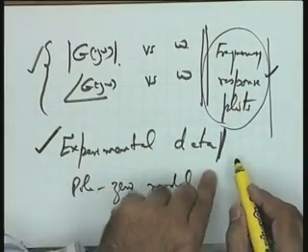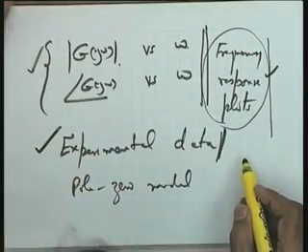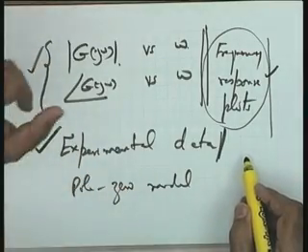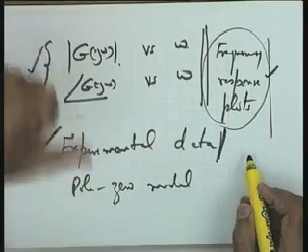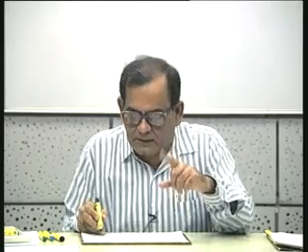So, from the frequency response data which you have got, you are getting a pole-zero model because you want to use the root locus method. However, in the process you have definitely made errors, because a complete mathematical model is not possible, a complete fitting will not be possible. So, you are working on an approximate model when you are going for a root locus formalism. But in the frequency domain formalism, since this step in between is not needed, you are directly using the raw data for your analysis and design.